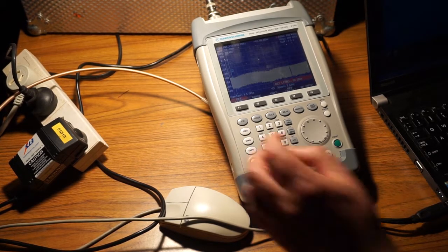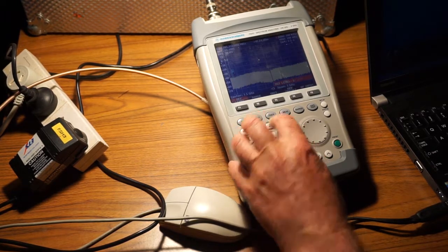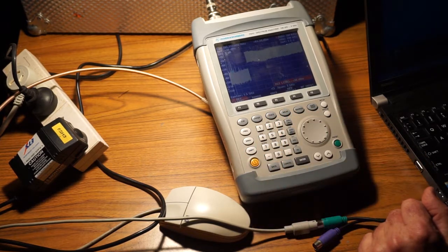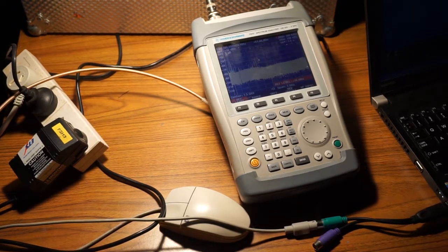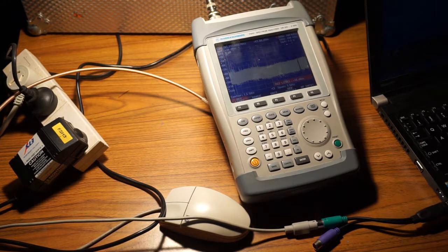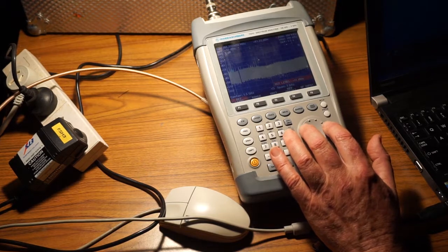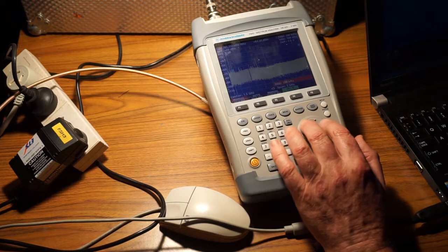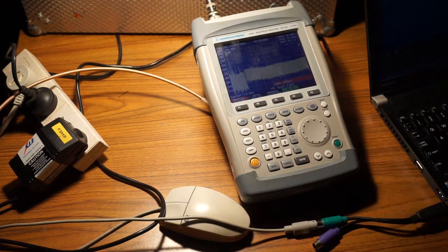So we'll make it go the other way. If we say minus 30 dBm, that now pushes it out, and it's lifted these spurs up, so that these have come up higher in the screen, but we still have a lot of noise there. So now how to get rid of that, if you wish to. We can change the resolution bandwidth. You can put the bandwidth down, and it scans slower, but the noise goes down.